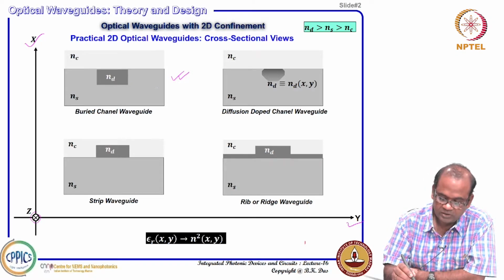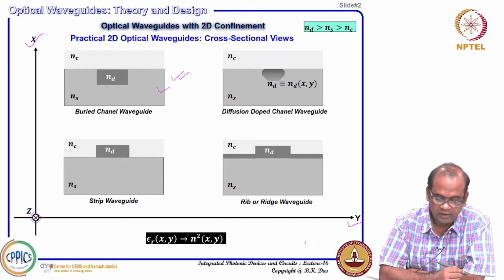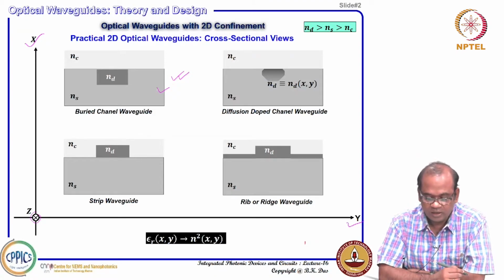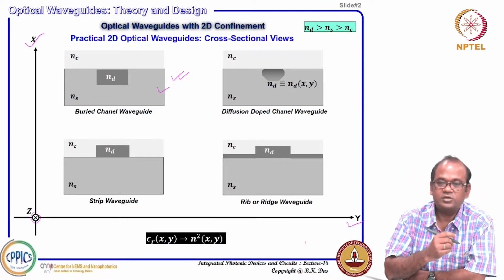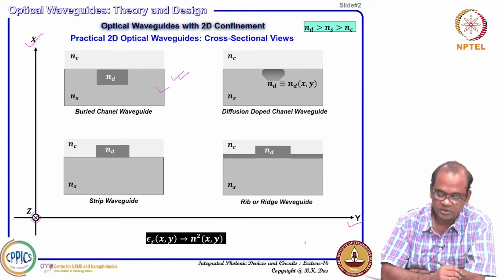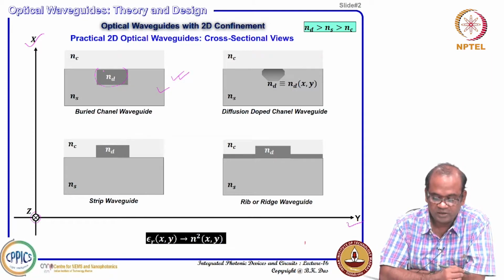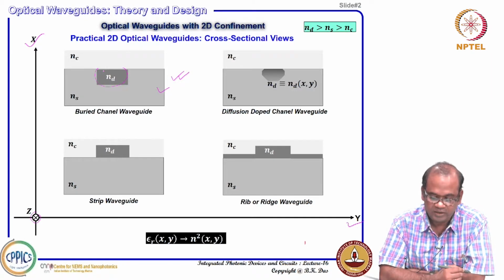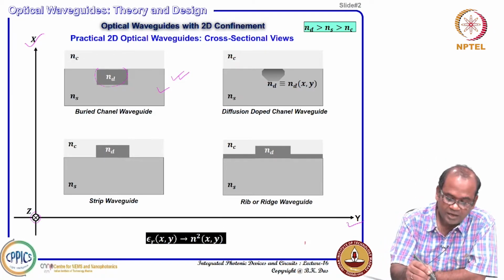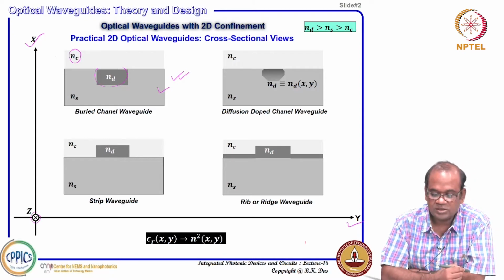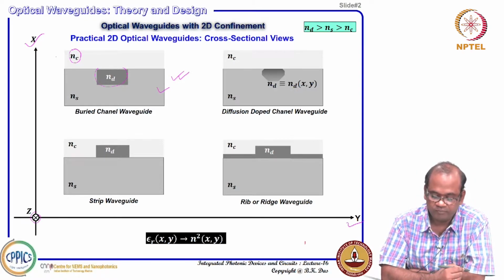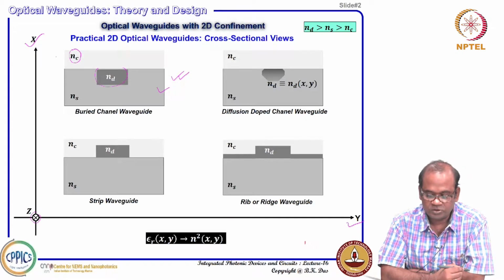And you can see that this bottom one is the so called NS, refractive index NS, S stands for substrate, and normally in silicon on insulator you consider that is actually the buried oxide. And then the actual device layer, the waveguide, has a little bit higher refractive index, which is ND as usual, as we have considered for the device layer, and the cover refractive index NC. So, this can be oxide, air, nitride, anything, okay, polymer even, all those types of things we can consider.